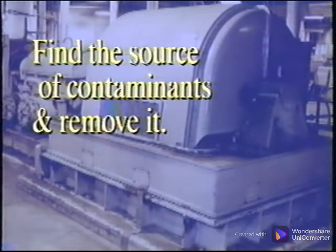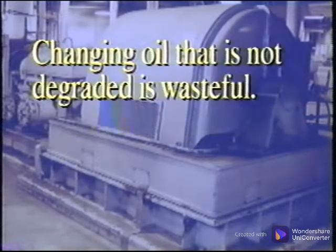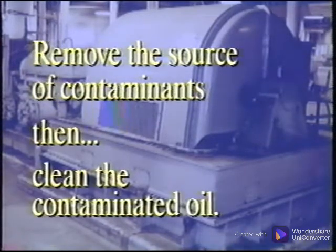Maintenance personnel must find the source of any contaminants and remove it before it degrades the oil and promotes machine wear. Simply changing the oil may remove the contamination in the system, but if the root cause of the contamination is not removed, it will quickly become contaminated again. Changing the oil when it is not degraded is wasteful. After identifying and removing the source of the contamination, then take the steps to clean your contaminated oil.